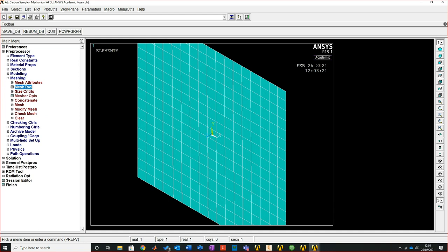Right, now, you kind of go, that's great. But that really does not look like the carbon fibre sandwich system that we're looking at. Now, because we've got this behaviour of orthotropic and isotropic interacting with each other, we now need to let Ansys mesh it for us and tell us what this would look like as a mesh, because we don't really have the geometry.